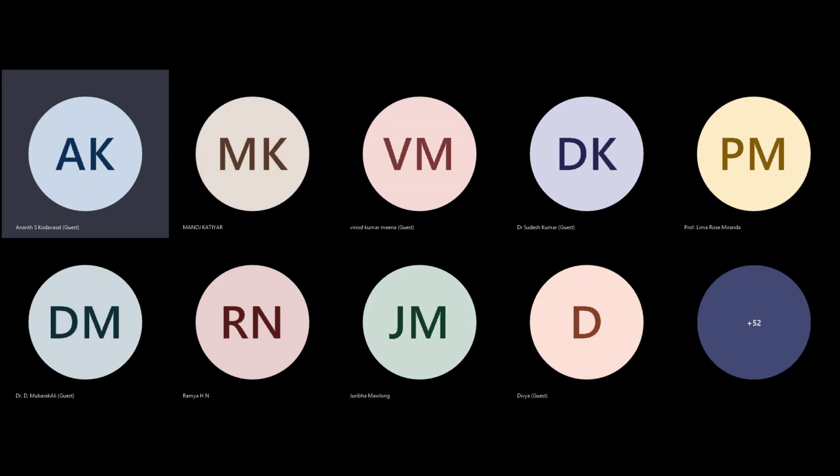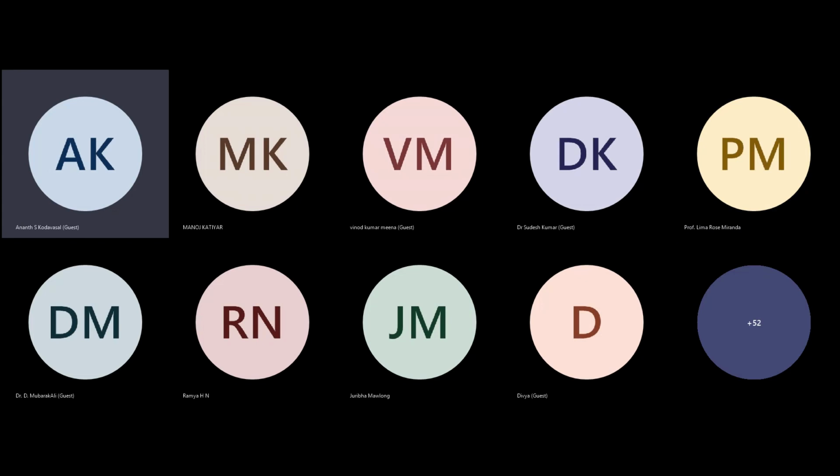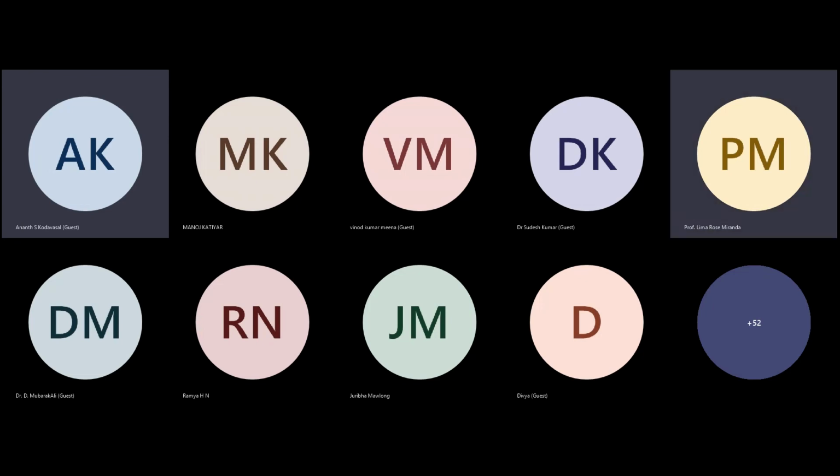Supposing you have 200 BOD. If the BOD to nitrogen to phosphorus ratio is 100:5:1, 10 milligrams is taken up by the bacteria itself, the carbon eating bacteria itself, and therefore only the remaining nitrogen has to be removed by the denitrifiers. So we have to do a lot of good analysis and calculation and computation before you design your mixed liquor recirculation rate.